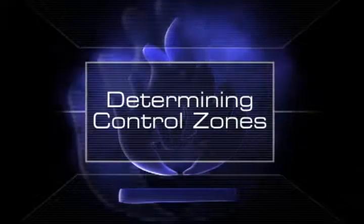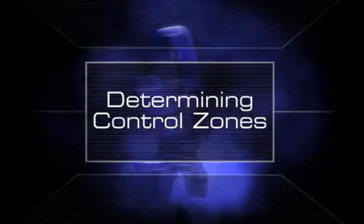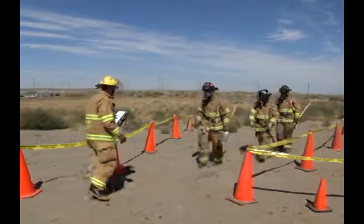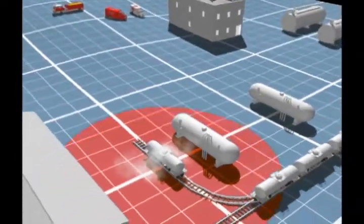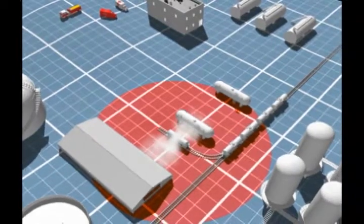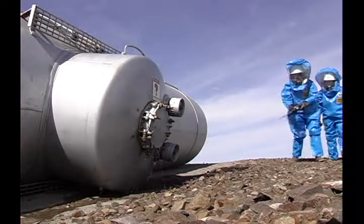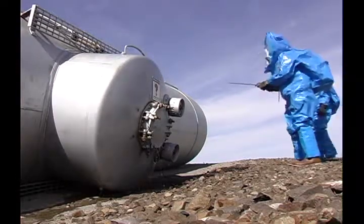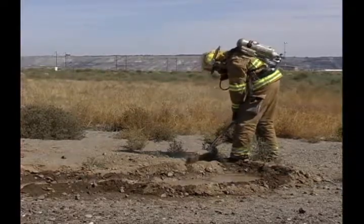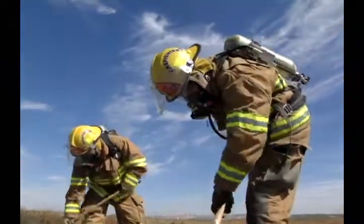Once your team has established scene control, designate control or work zones. Three types of zones are typically used in a hazmat response. The hot zone is the area immediately surrounding the release that requires the use of PPE to enter. Generally, technician-level hazmat teams are the only personnel allowed to enter this area, as they are trained in advanced monitoring, sampling, and offensive actions. Ops-level personnel with the appropriate PPE and monitoring equipment may enter the hot zone to perform defensive measures if necessary.